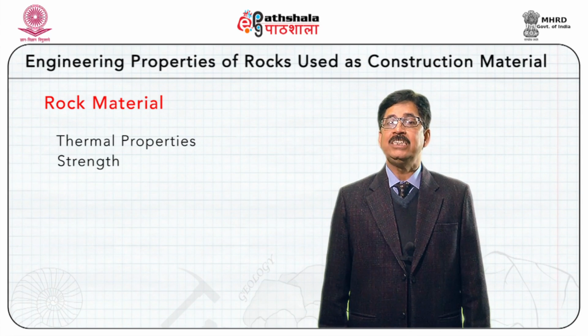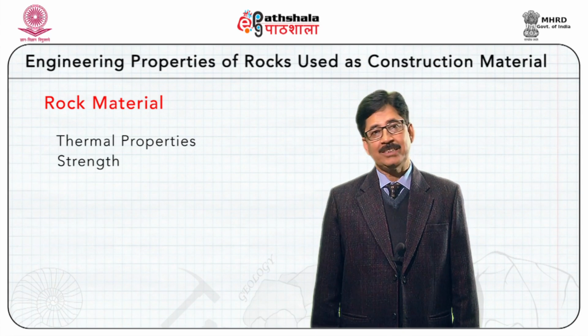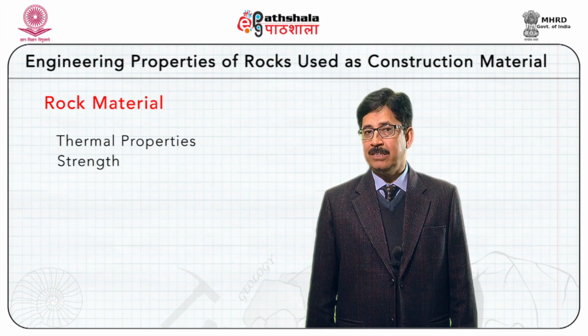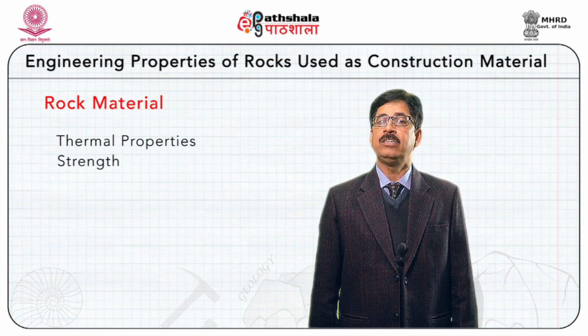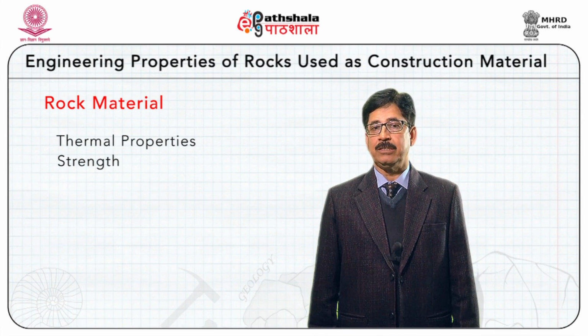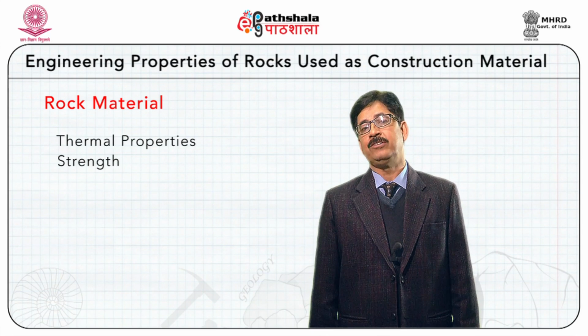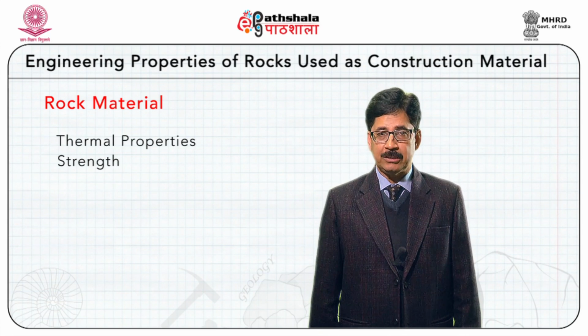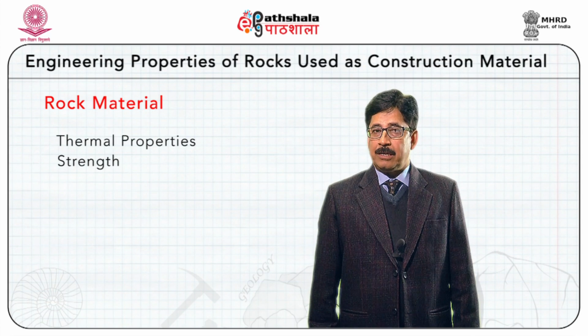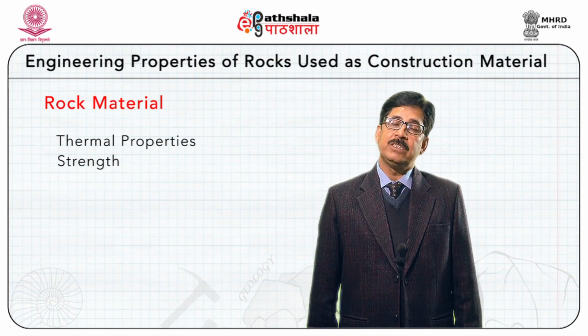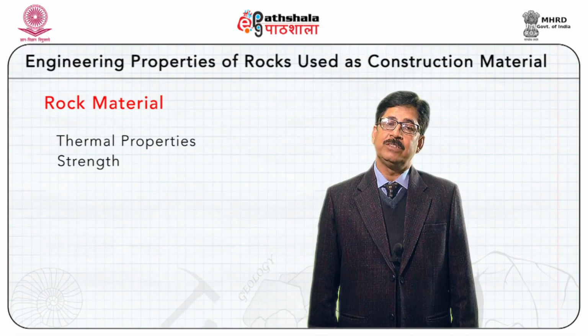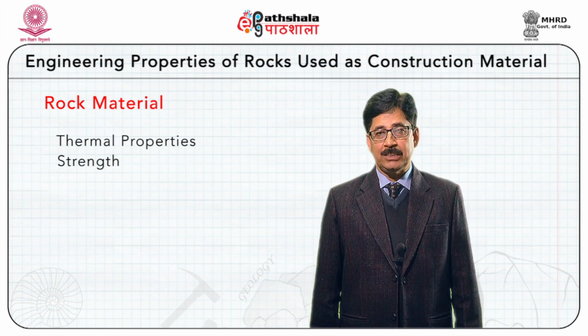We can measure these strengths using different instruments, as unconfined compressive strength and confined compressive strength, using a UCS machine and triaxial testing machines. The uniaxial compressive strength as well as triaxial compressive strengths can be related to the density also.